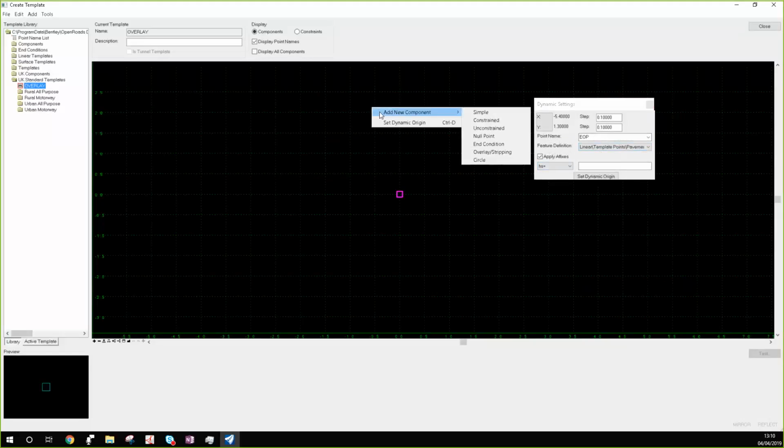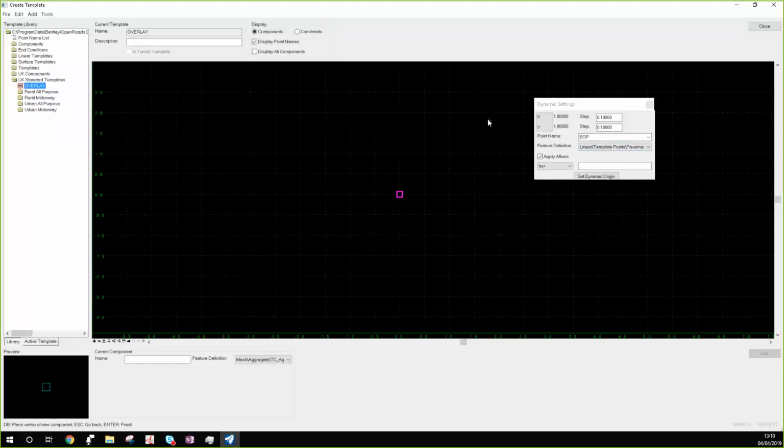If I right click, I have access to the creation of a new component. It will be constrained by the width and the slope. The first point would be the origin of the template. And if I right click, I can uncheck the close shape because I would just want it to be a normal element. And I will mirror the components, so like this it will create both sides at once.